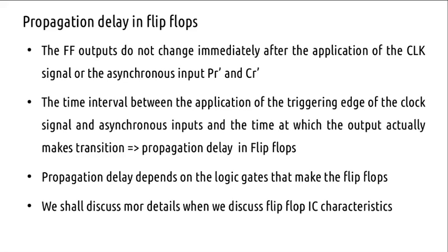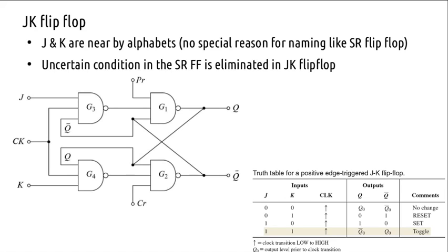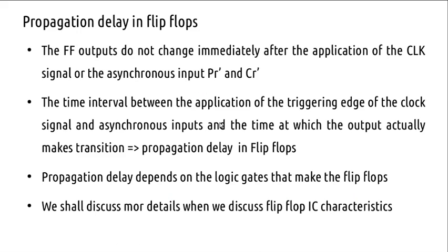There is a finite propagation delay through the logic gates. Actually, we are talking of not one gate, two levels of gates are there. We are applying an input, there is a propagation delay in this gate, then there is a propagation delay in this gate, and there is some time. Even if all are in microseconds, there is some finite time for these signals to reach the output and your outputs to be asserted. So that is what we call the propagation delay.